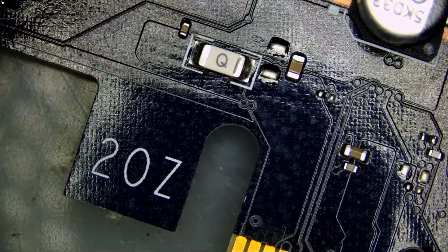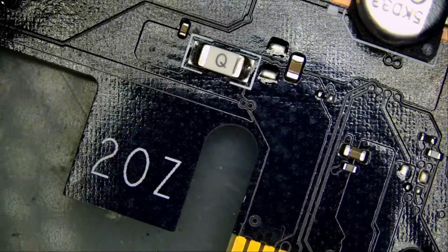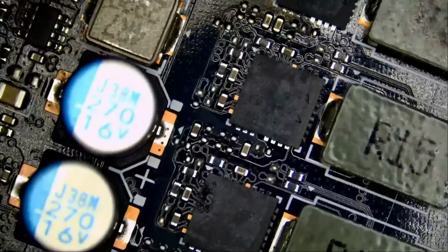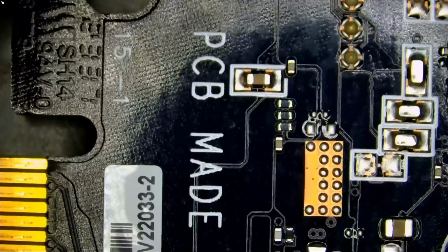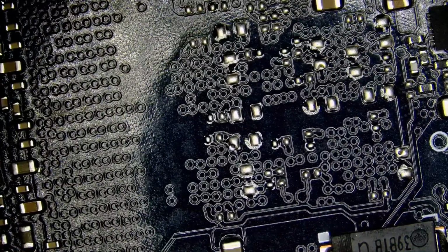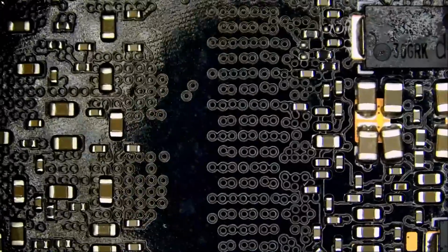Let me measure this fuse here. And 0 ohms. The other components, no issues. Flip the card, look on the back. We're going to inspect the data lines. Because as you know, a customer who wants to know the exact component probably tampered with the board. They probably opened up the video card so they could inspect the inside.